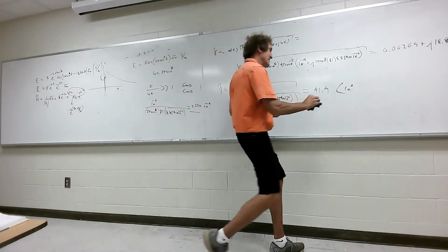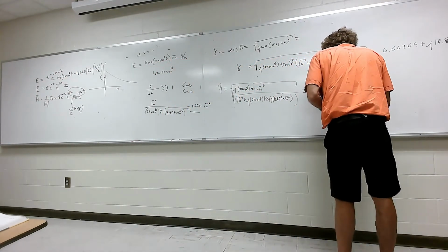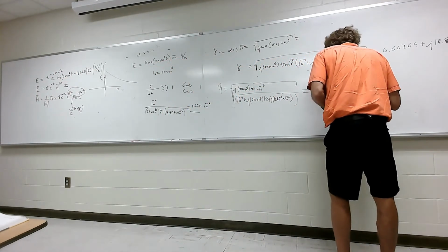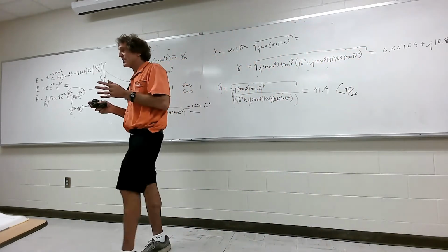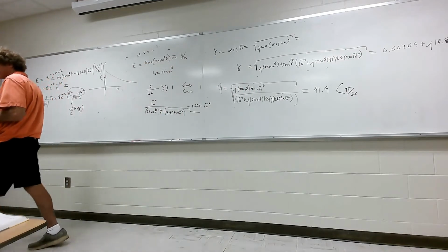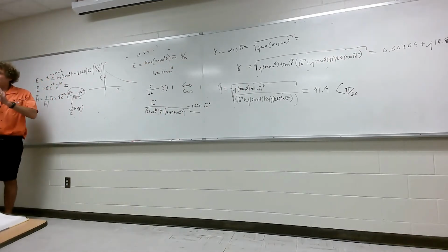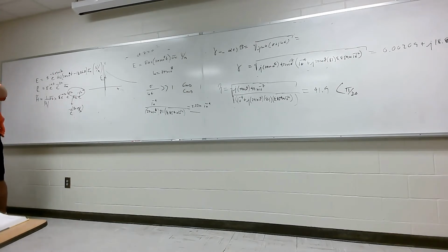So I won't add to the confusion that, if you have Dave Irwin's book, a lot of times you'll see cosine of omega t plus 10 degrees. When you turn it into a phasor, it's just a magnitude at 10 degrees. Frankly, 10 degrees should never be next to omega t, because omega t is in radians, right?